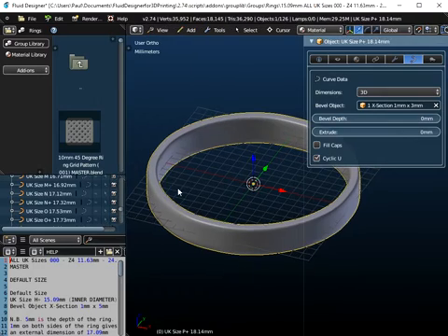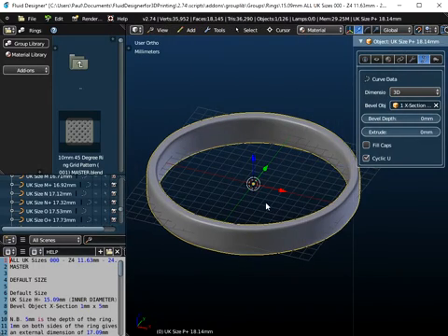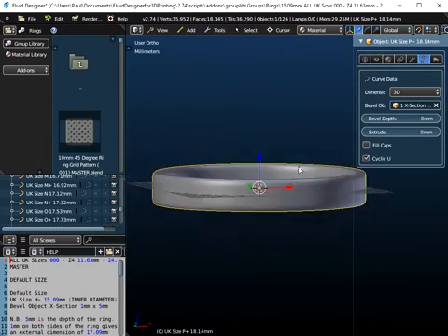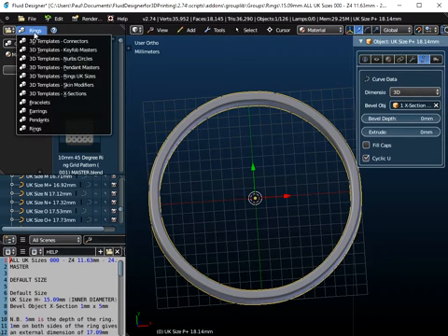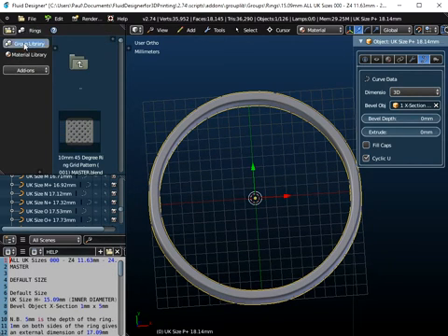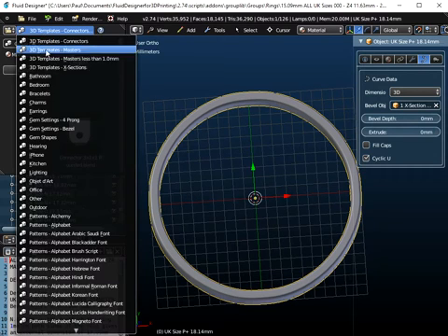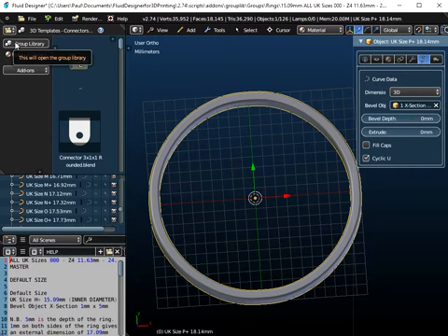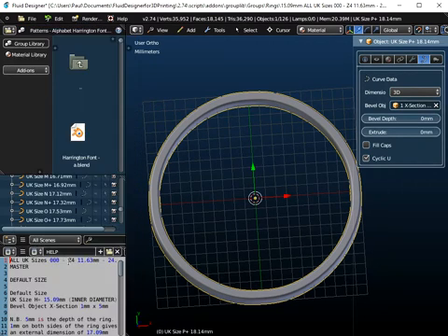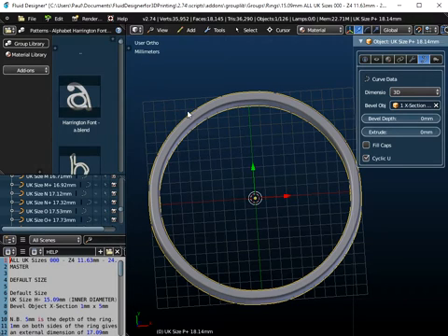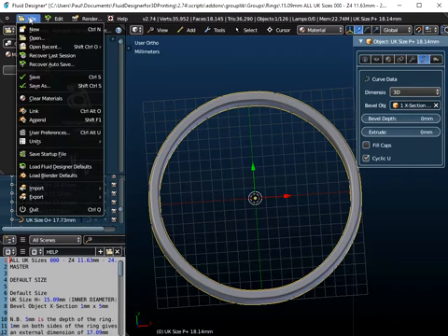Now the next thing I need to do is I want to add a letter A to my workspace, as I showed you previously, and it's not listed there. So if you can't see anything in the drop down list here, just click the button at the top and it will refresh the list. I want alphabet Harrington font, and I'm going to append this object to the workspace. And we don't drag and drop it, we go to append.